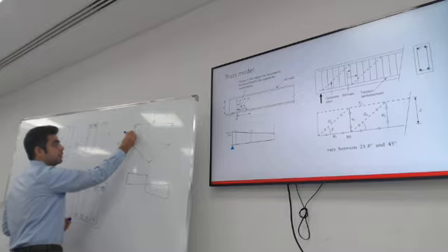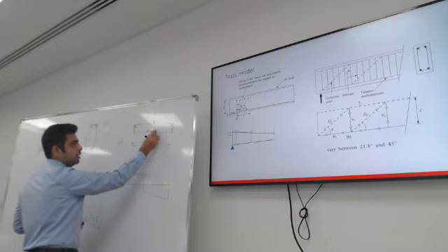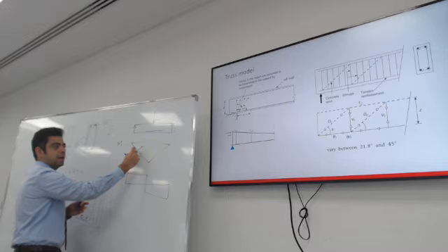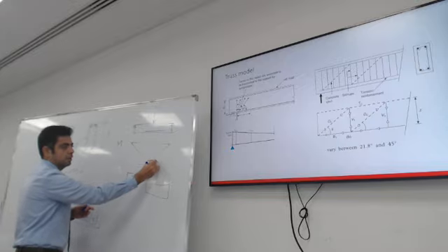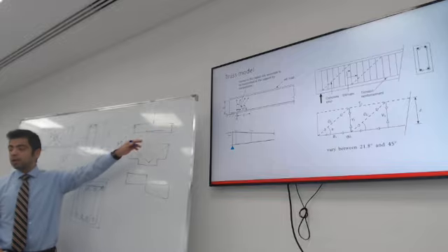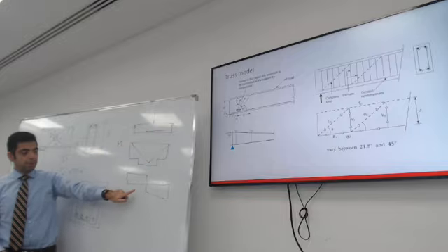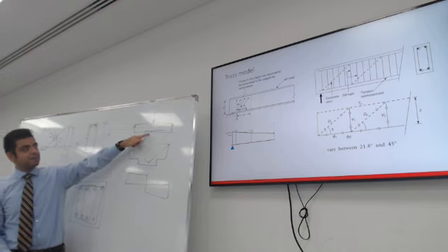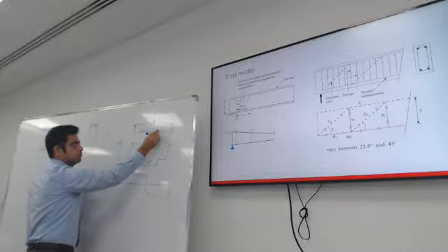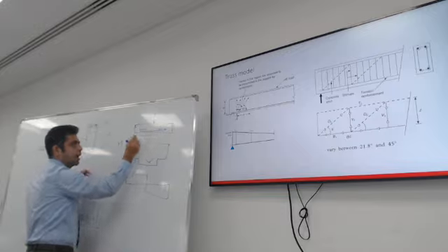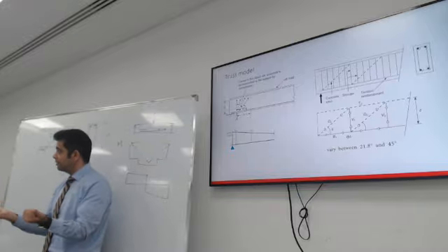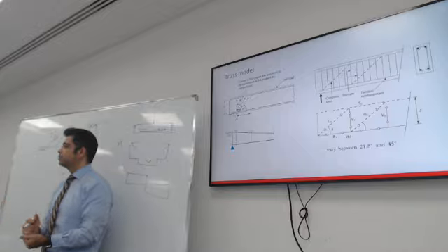If this beam has a bottom reinforcement here, this bottom bar is to resist this moment. Because of the existing shear, I need to extend the bar longer to take into effect the increase in tension in the bottom reinforcement due to shear.